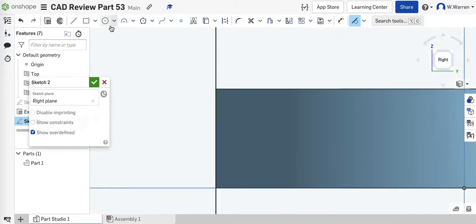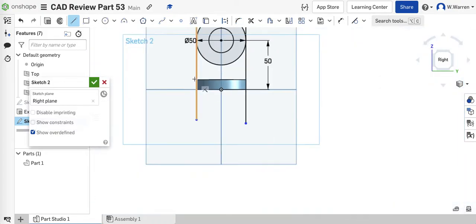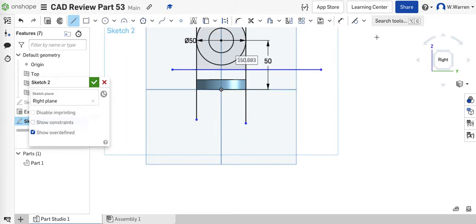Let's just zoom in and put a straight line there. So let's put a straight line right about there. I think, you know what I'm going to do? I'm going to do the same thing again, because I don't want to eyeball it. I really don't want to eyeball it. I want this to be correct. Is it horizontal? Yes, it is. Let's put it in the right place using the dimension tool, because I know this is 10 millimeters thick, right? This base here. So where do I want that line to be that closes out this geometry? I want that to be at that same spot. So here to here, what I'm going to do is 10 millimeters.